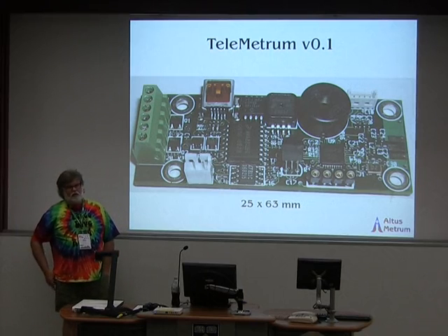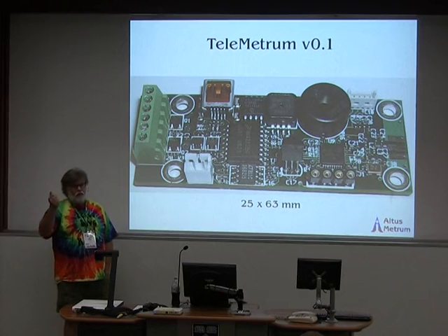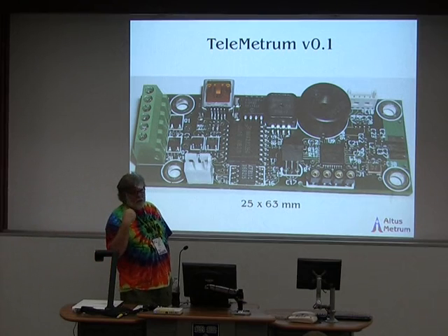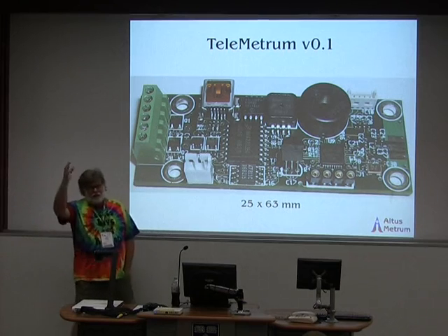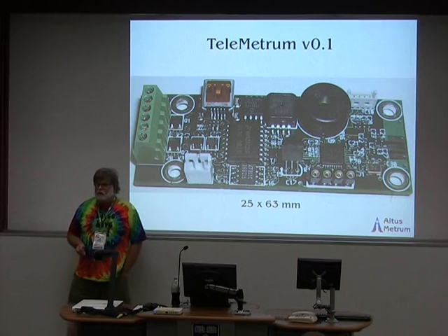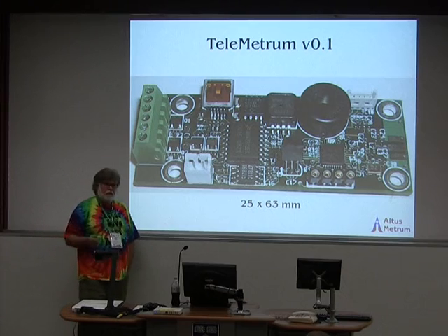Yeah, so if you're using a handheld 5-element Yagi on the ground and a quarter wave whip in the airframe, and things are oriented right and you're in free space, i.e., approximated by atmosphere, with clear line of sight without a lot of multipath reflections from the ground, you ought to get something like 30 kilometers range. That's with 10 milliwatts, okay? That's an error-free data stream at that range.